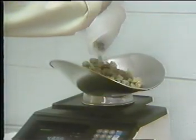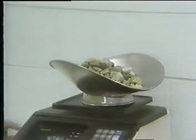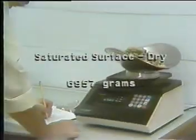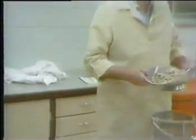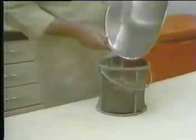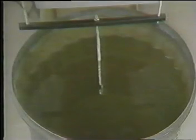Immediately after the test sample has been surface dried, weigh the test sample to the nearest 0.5 gram or 0.05% of the sample weight, whichever is greater. The weight of our saturated surface dry test sample is 6,957 grams. Immediately after weighing, place the test sample into the sample container to determine its weight in water at 73.4 degrees Fahrenheit plus or minus 3 degrees. The container and sample should be completely immersed during weighing.